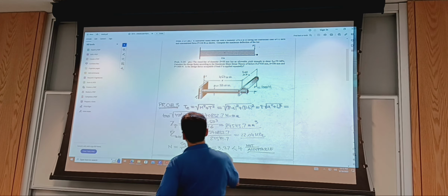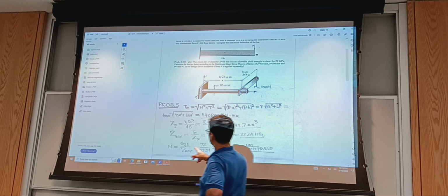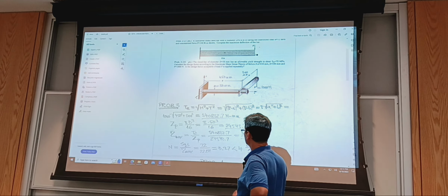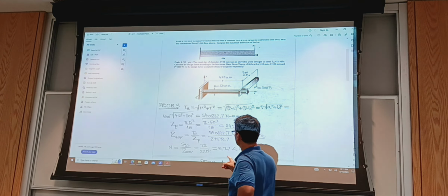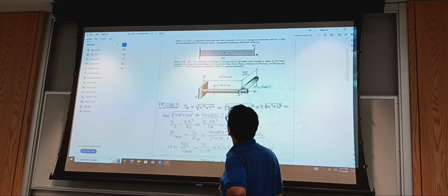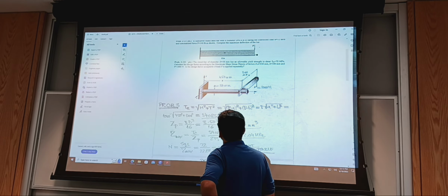Okay, so you calculate the maximum shear stress with this, and this is the maximum equivalent shear stress, because we use the equivalent torque. Okay, and yeah, with it you calculate, because yield strength in shear is directly given, the design factor by just taking the ratio of the yield strength in shear over tau max. It is less than 4 for fluctuating load, and it's not acceptable.